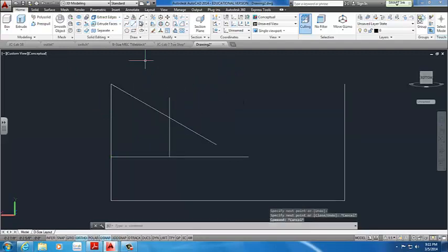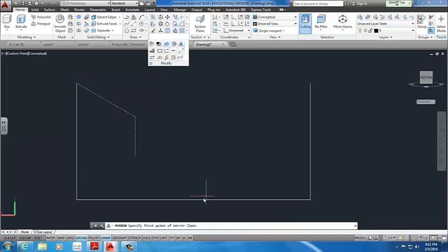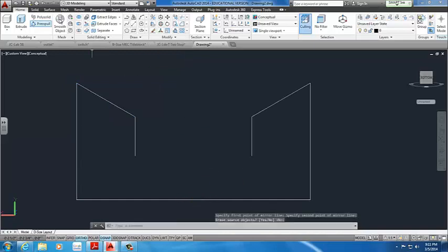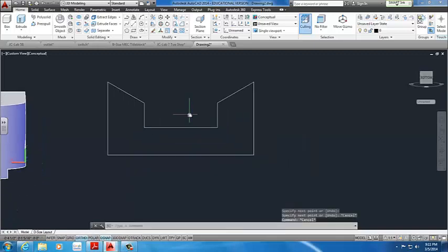We can trim out that material that we don't need, which is these two, and delete the remaining lines that we're not going to use. We take these two items, we mirror it across. So you go to modify, mirror, using the midpoint to give us this shape, original shape. At which point we extrude out, create the circles at the center, and subtract them out.